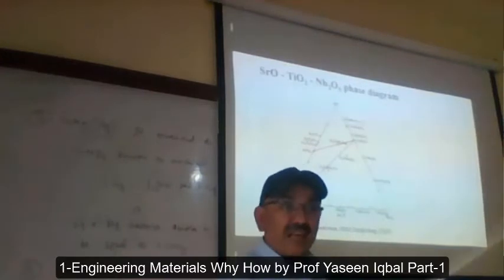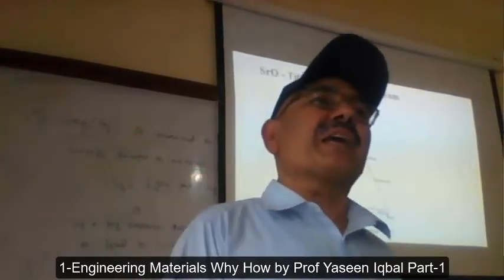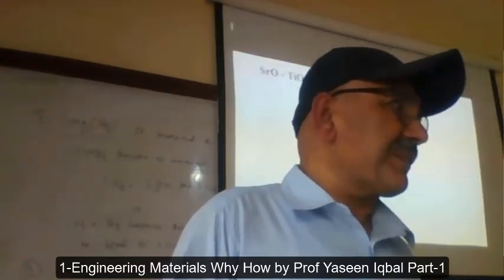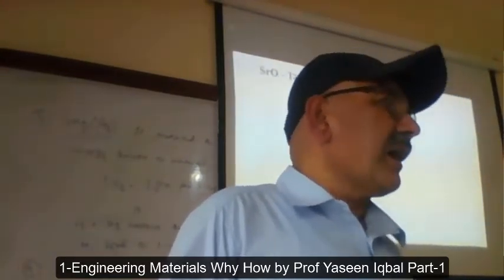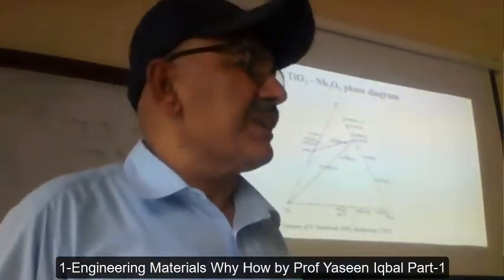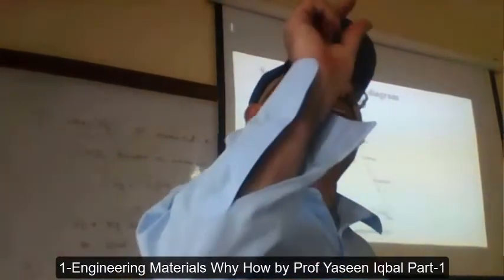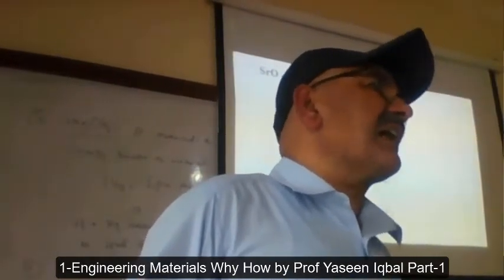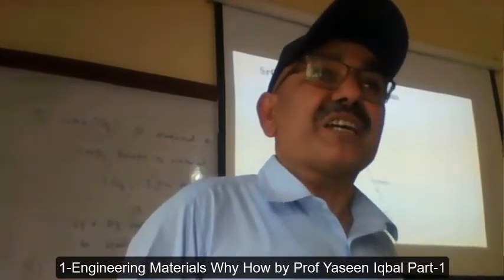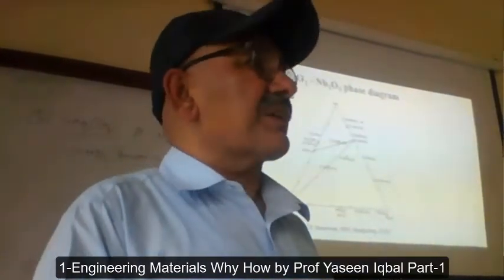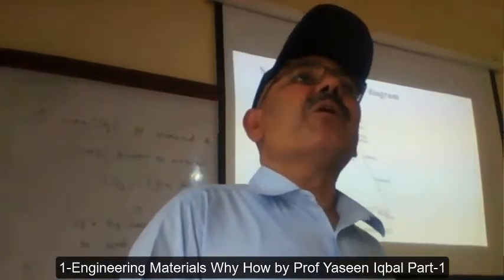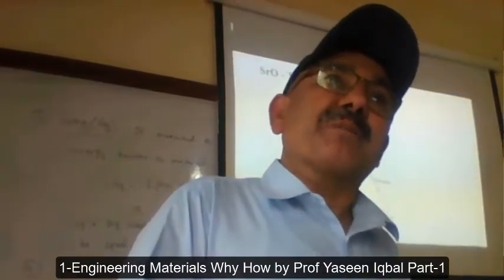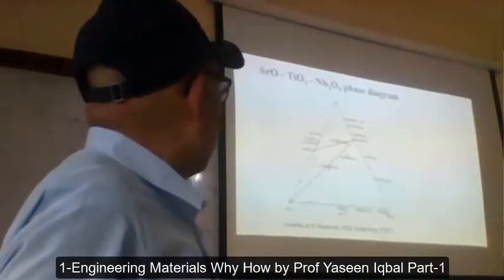If the equation is not balanced, then whatever you are making will not be a stable phase. There will be deficiency in it, deficiency of oxygen. Deficiency of oxygen in a material structure means that you will have gaps, unfilled cation anion sites inside the crystal structure, and those unfilled sites will again confer either good or bad properties depending upon the application of the material.